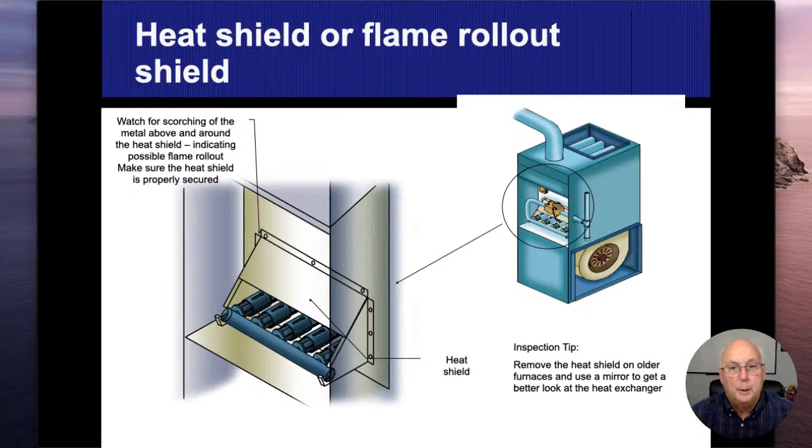Everything else is going to be 20 plus years old. And even with these old natural drafts, they're going to be over 25 years old. I may run into one that's still working, but I really haven't seen one in a long, long time. So I think it would be very rare. But we would unscrew the flame rollout shield, get our mirrors inside of there, obviously, and look for any sort of rust, cracking, holes, and so forth.